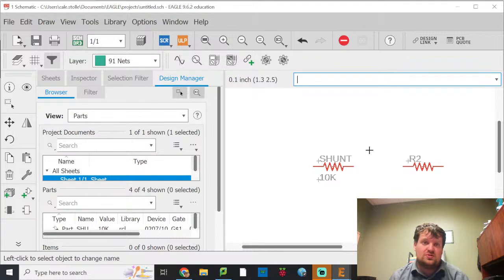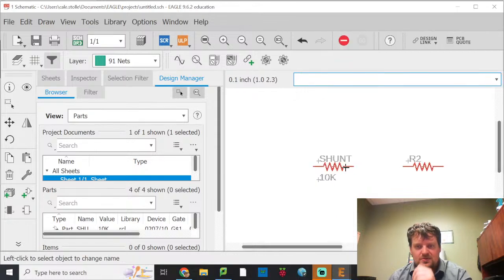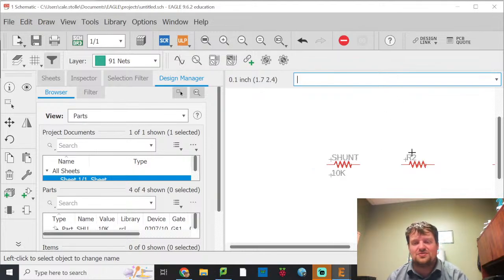If R1, R2, R3, R4 are meaningful to you, go for it. And when you want to change, you have to click on this crosshair right in the center, right click on it, and that's how you open this up. If you just right click on the side of it, it'll beep at you often, which becomes very annoying quickly. Eagle is not the most user-friendly interface, unfortunately.